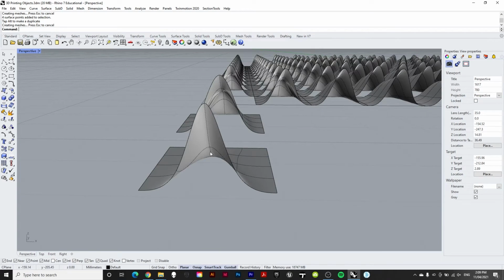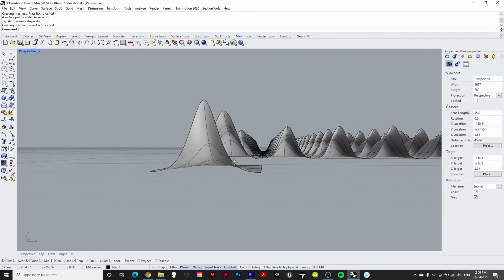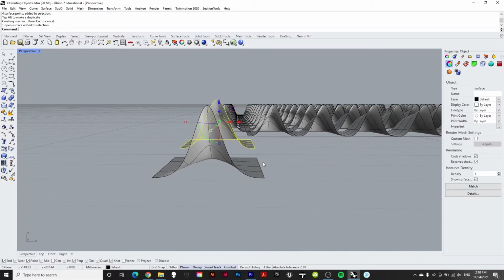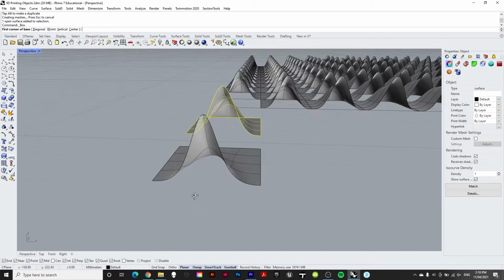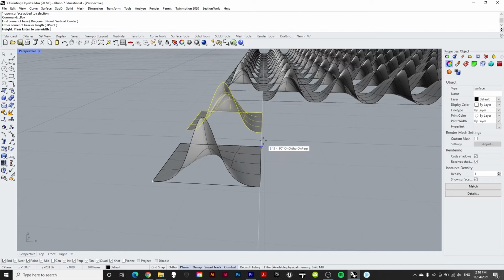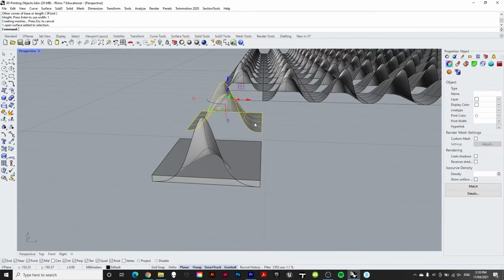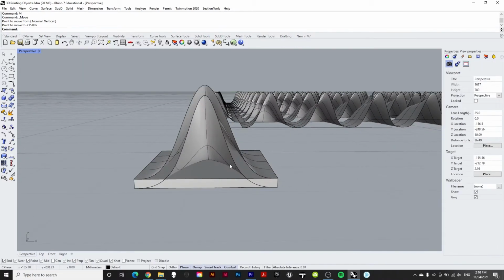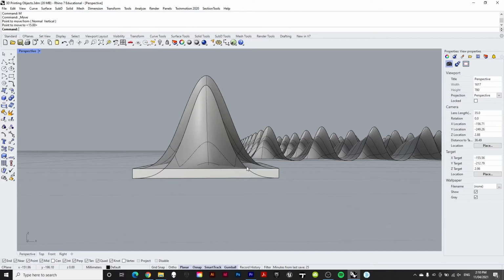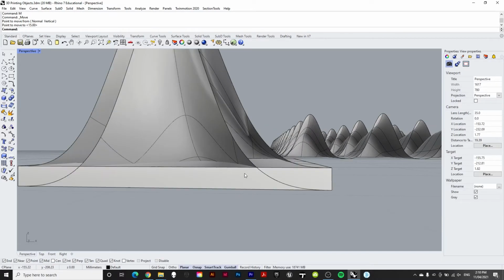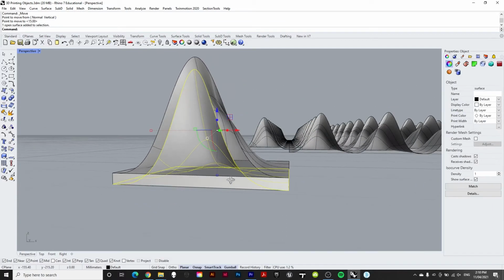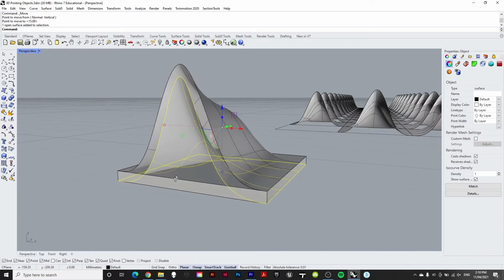Okay, so that's that. Next thing we can do is actually just create an additional geometry to remove some of this horizontal surface that we have inside here. So what I'm going to do is I'm going to take a slab at 1 millimeter, and that's going to be our offset height between these two anyway. So that's going to mean that it's taking out all of this slack that would be inside there and now covering it up with a base. So we end up with the only horizontal portions that we have to be worried about now are the ones inside this cavity in there.